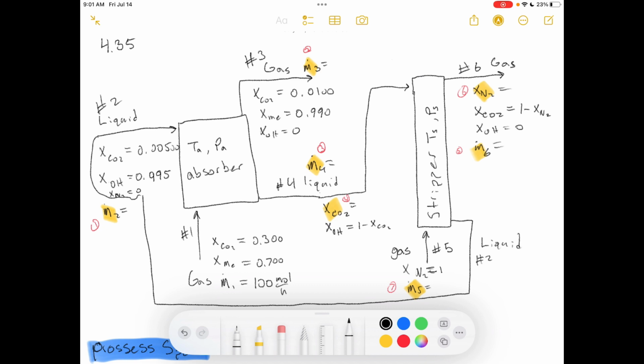90% of the CO2 in the liquid fed to the stripper comes out of solution in the column, and the nitrogen-CO2 stream leaving the column passes out to the atmosphere through a stack. The liquid stream leaving the stripper tower is the 0.5 mole% CO2 solution recycled to the absorber.